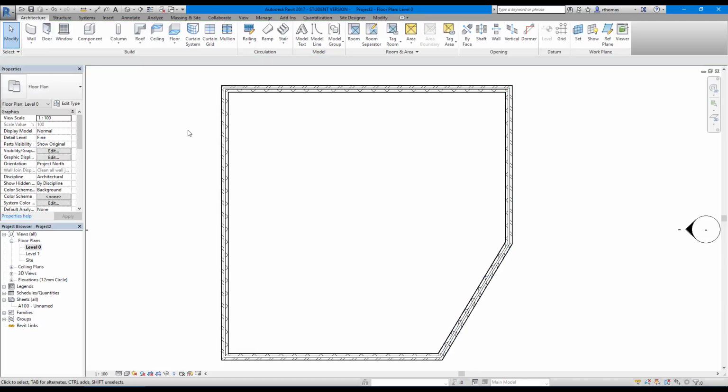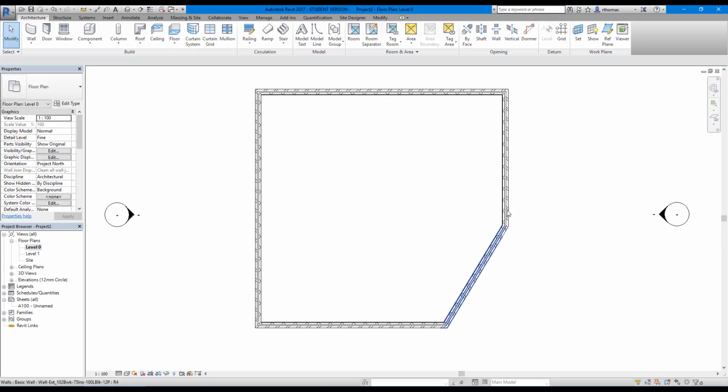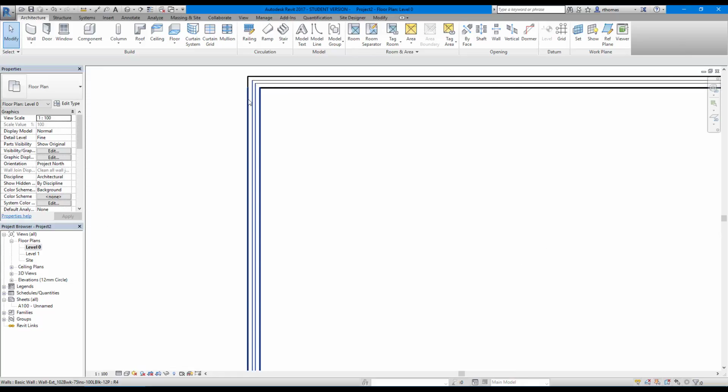And then your plaster will be on the inside and your brick on the outside. So that's exterior walls. They do all join up together. As you can see here, I started up here where I brought this wall back in. It's actually joined up, so you can see the air gap running around. Those other bits are interconnected now.